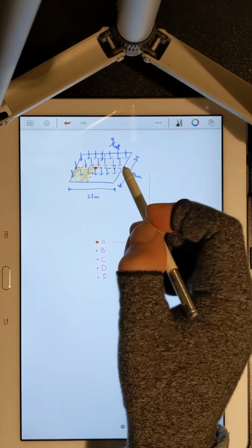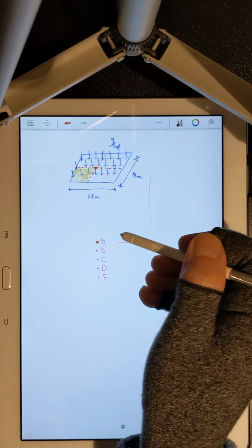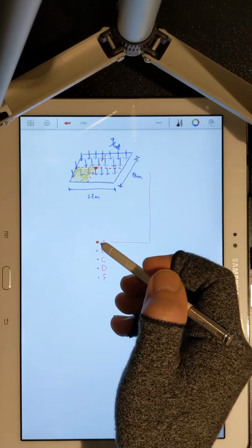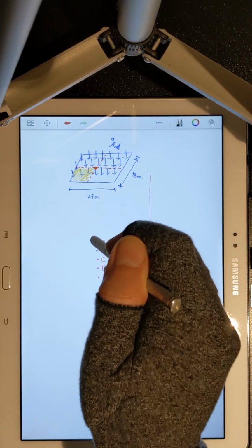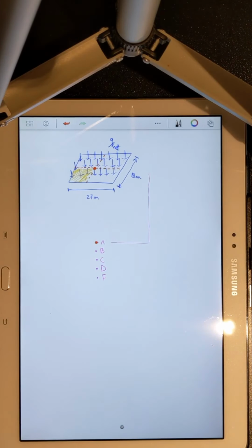And we repeat this 4 times, or we multiply this value by 4 to get the total value of net stress at the point of interest after dissipation with depth. And this is, again, our strategy.